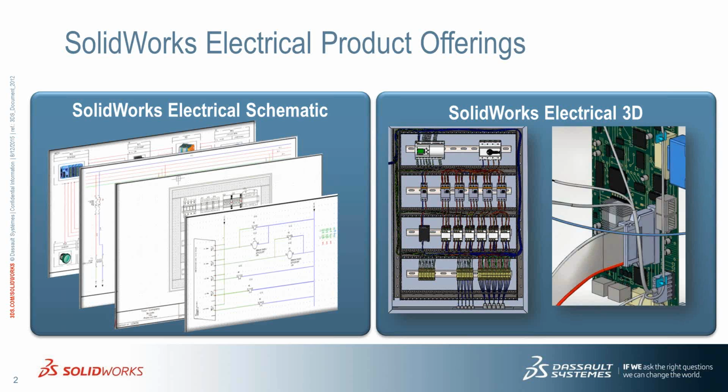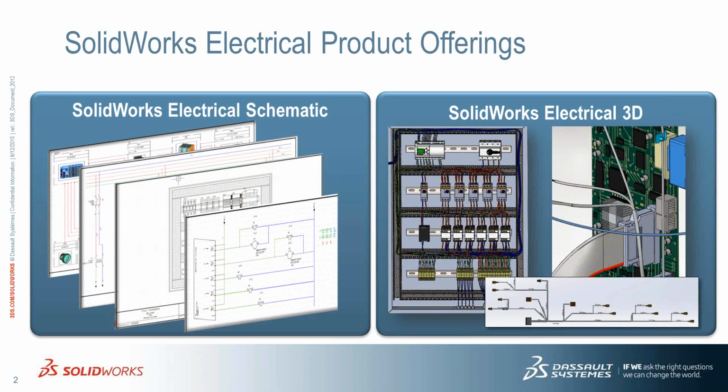You can also input harness and cable information, which will allow you to get manufacturing drawings of your harness or cabling so that you can use that information for nailed down production to create an actual harness in a one-to-one relationship. Well, in the background of SolidWorks Electrical, there's a SQL database. This SQL database allows the tool to constantly talk in real time, allowing information to be sent back and forth and making sure that all of your drawings are up to date.